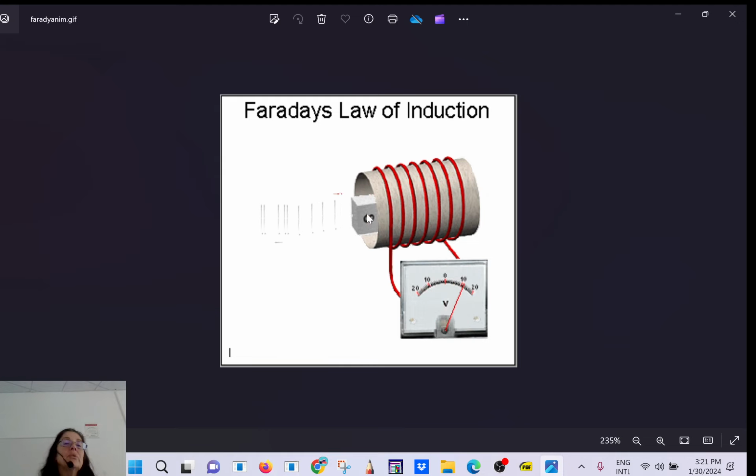So it's being pushed in, pushed out. How many times per second? 60. So 60 times. In 1 second, you go in, out, in, out, in, out, 60 times. So that will be the frequency. That's where you get to your house. Here, you see the hot connection, the small one. It's going to be what? 120, 0, minus 120, 0, 120, 0, minus 120, 0, and so forth and so on.